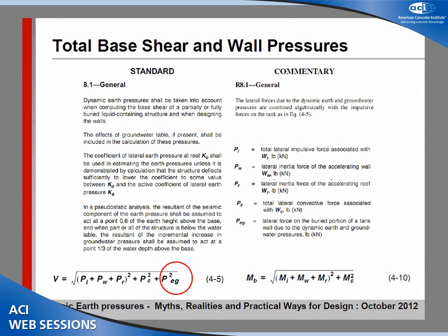What it says in chapter 8 is pretty much that the structure has to be designed considering dynamic earth pressures, but it doesn't really recommend a particular procedure to calculate those dynamic earth pressures, although the assumption mostly is that you will be using Mononobe-Okabe or some method like that, which is like the most popular.